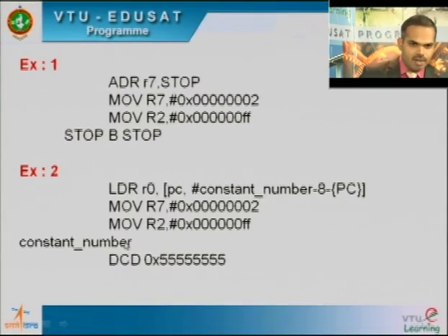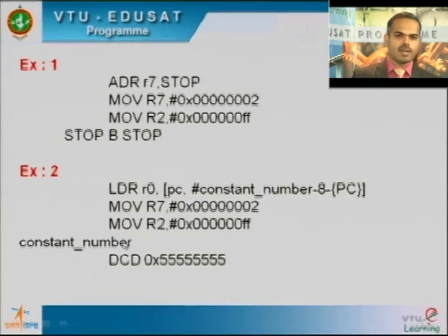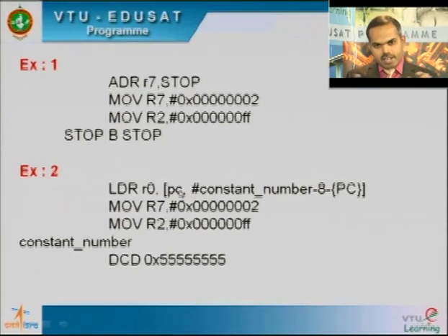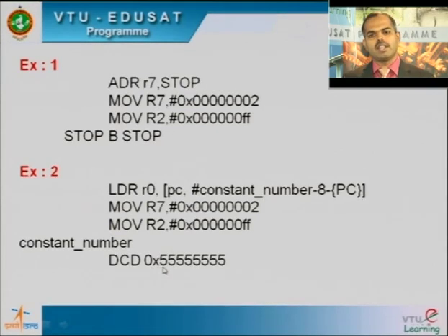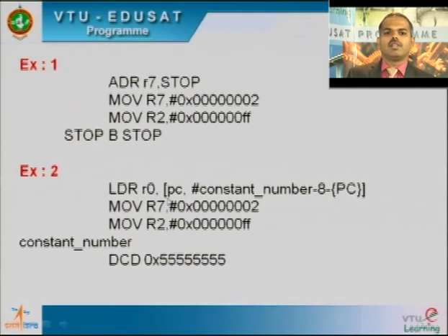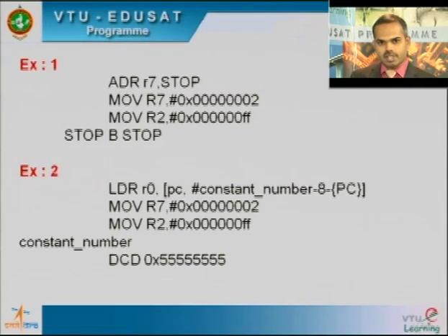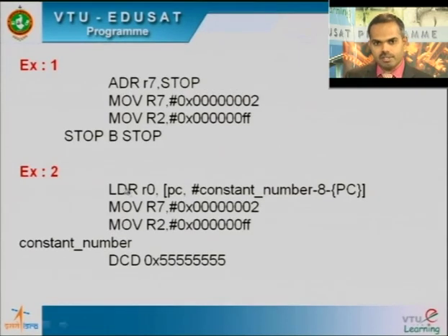That constant number value means the memory location of that constant number will be given to this instruction, that gets added to PC. That whole will form an address where this 0x85 is stored. From that address, this 0x85's value is fetched and then loaded to register R0. So that's what happens when we say LDR R0, =0x85. The assembler internally converts that to this instruction.